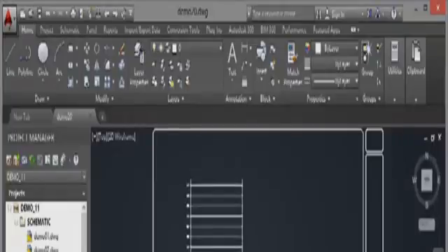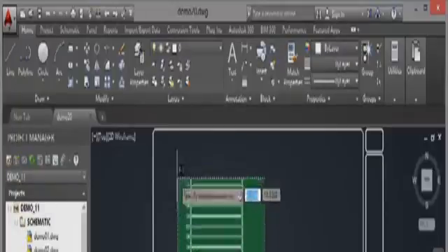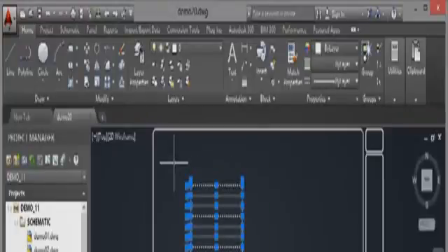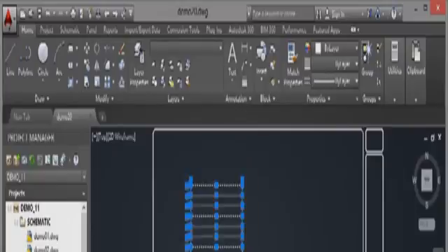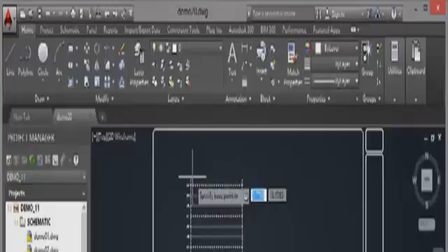Repositioning a ladder in a drawing is very, very easy to do. You simply utilize the AutoCAD move command and utilize your object snaps as well. One of the nice things about a ladder is it's got some nice endpoints to snap to. If I select all of these objects like so, using either a crossing or a window selection like that, I can just right click and on the shortcut menu I get the move command there as well. So I can use either the shortcut menu or the move option in the AutoCAD home tab on the ribbon. So if I click on move now, it says specify a base point. So if I snap to that top point there using the endpoint snap, I can drag that up here like so, get that nice and neatly in the corner, and there's my first ladder moved nice and neatly.